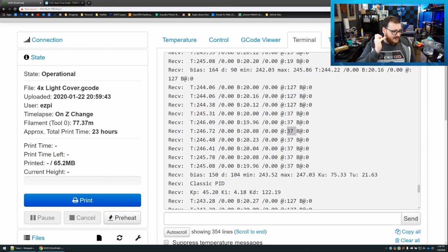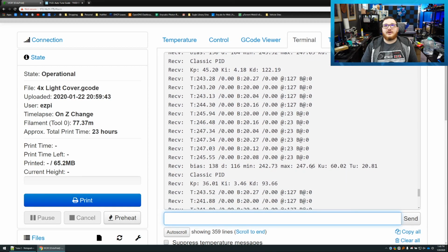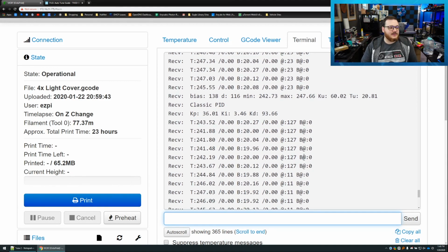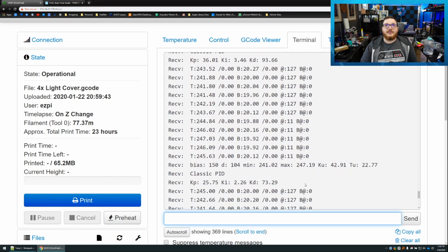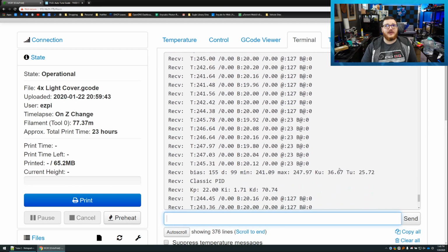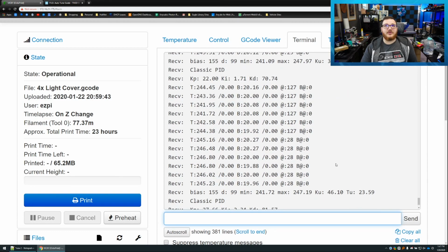What do I think is better, Meanwell or ATX? Just go with the Meanwells. ATX is more of a pain, and there's no warranty on those because you're cutting up the connectors. Unless you buy like $50 worth of plugs, it's way easier and cheaper and just as good to use a Meanwell. The only thing is usually an ATX power supply will have power factor correction, so it's a little more efficient. But personally, I wouldn't waste time on an ATX, especially since most of the machines are 24 volts. Meanwell makes power supplies for 12 and 24 volt and 36 and 5 and all sorts of values, so Meanwells are not just for 24 volt printers. We actually carry 12 and 24 volt Meanwells.